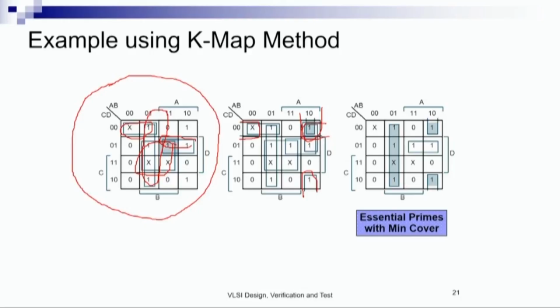these three prime implicants here, here, this one and this one. These three prime implicants are sufficient to cover all the ones in the function, and therefore it is a cover over essential prime implicants, and we do it through the Karnaugh map in this way.